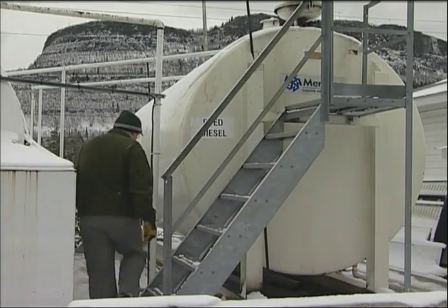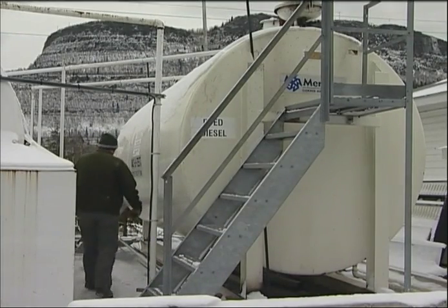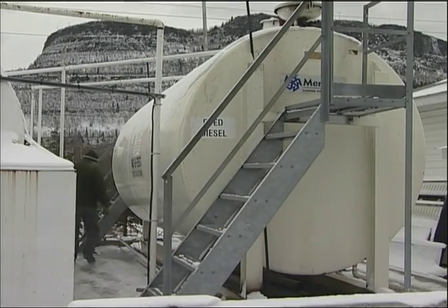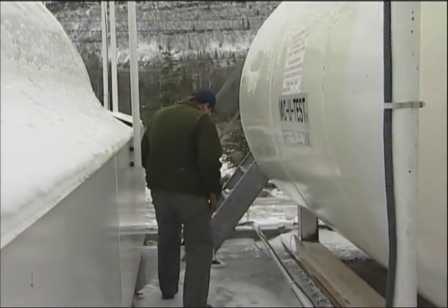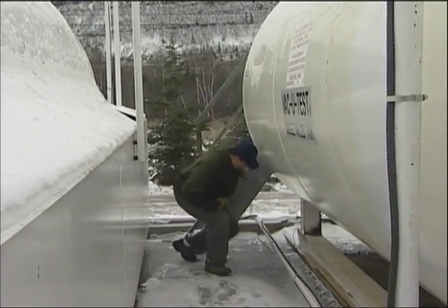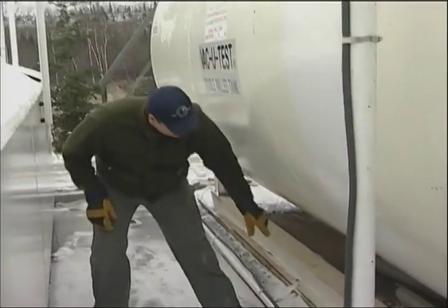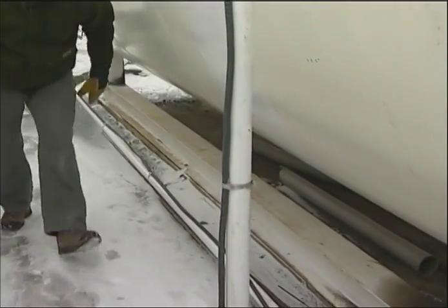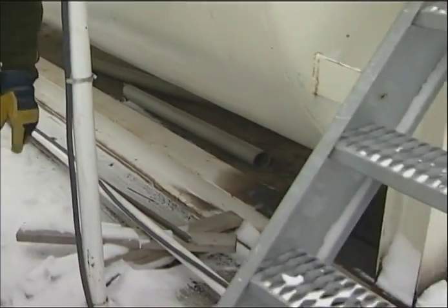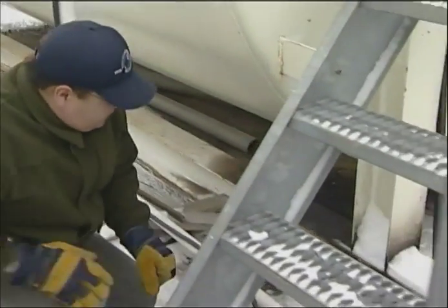Always do a complete 360-degree inspection of your above-ground tank daily. Check to make sure your tank is securely grounded with a wire cable securely attached to a ground rod or grounding plate that has been buried in the ground. Inspect fuel saddles on the bottom of tank to ensure tank is not sinking into the ground causing stress to tank structure.